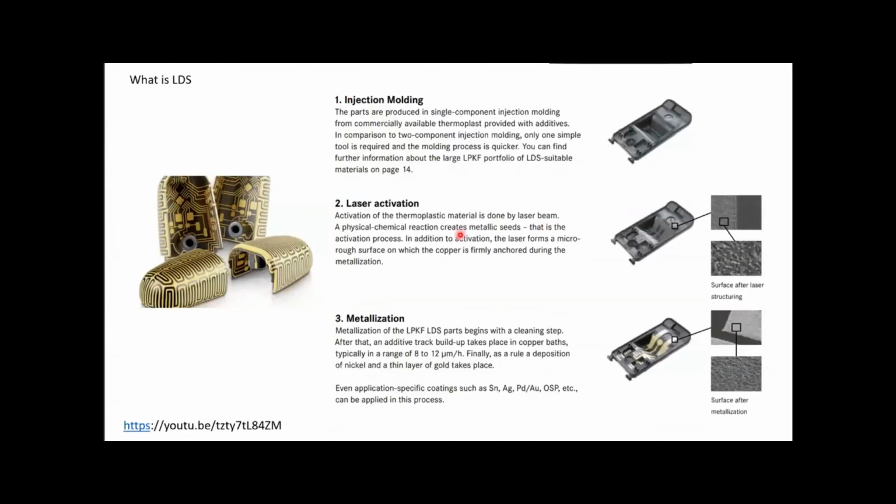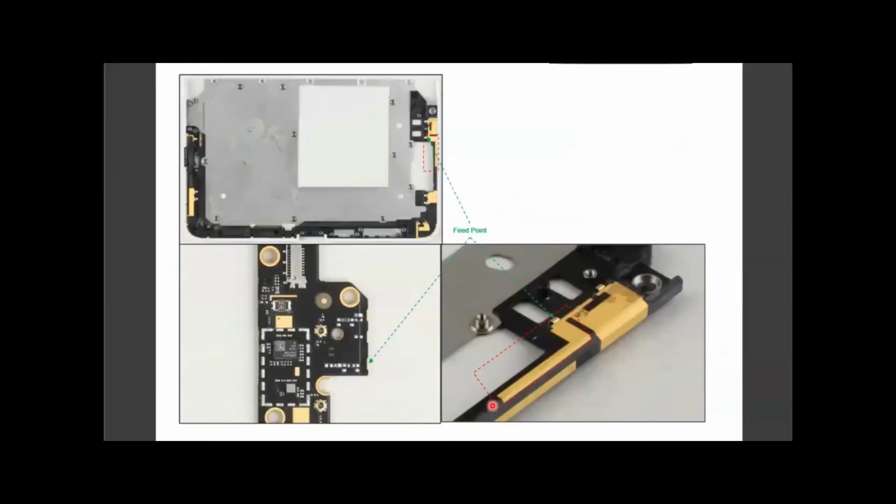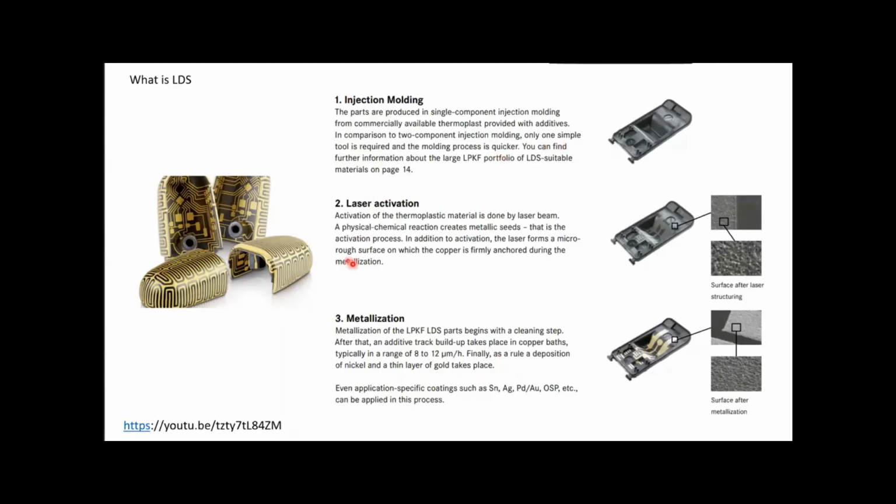And then I was going to go through LDS. There's a video on LDS, but I think we'll have to skip it because of time. LDS is a process with gold plating on the plastic, and this is the process for it. It's an injection molded part, and then we use a laser to activate the plastic.